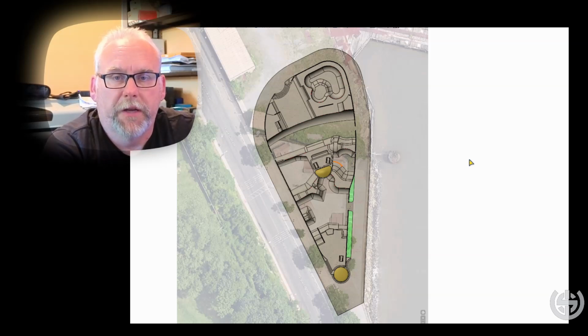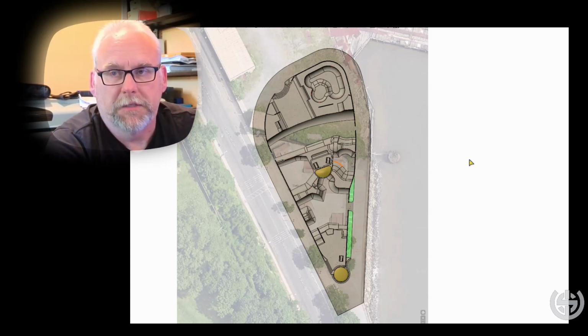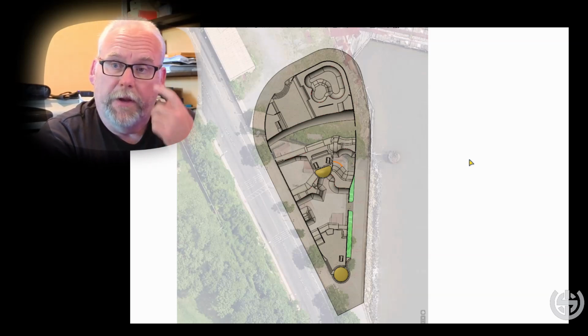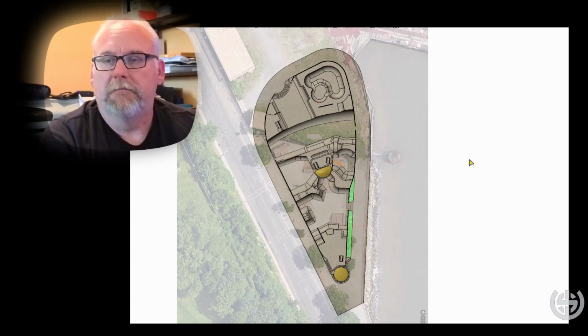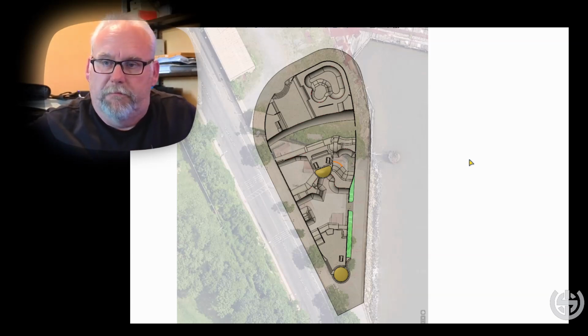Make sure all your drains are oversized. If you think a 4-inch drain's big enough, make it a 6-inch drain. Your parks department guys will be very happy that you did. If you really want a maintenance free park, talk to the parks department. They'll maintain the shrubs and stuff because it's their job, but from a cost standpoint, you want as little of that greenery as possible because it just means busted plastic and things that don't work, sprayers with the heads broken off of them.